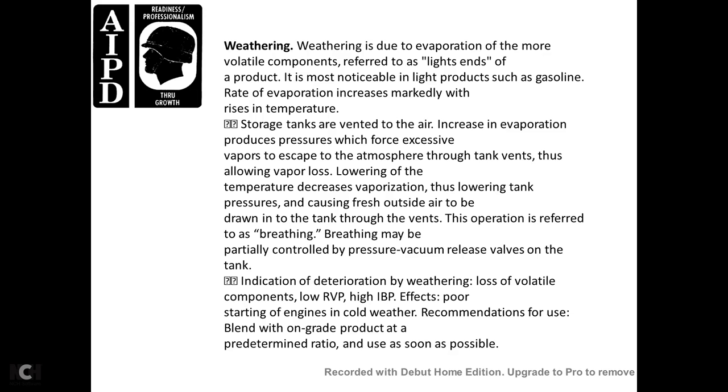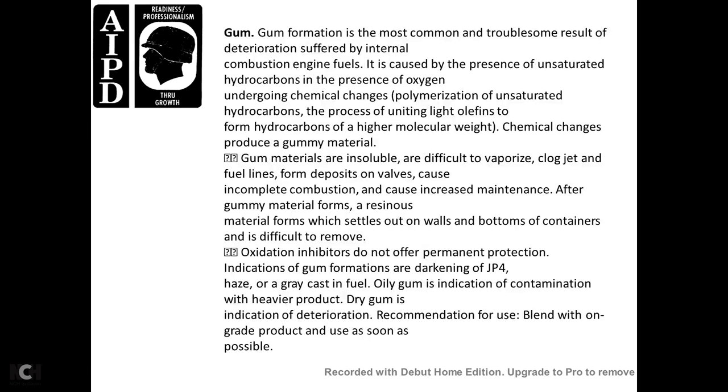Identification of deterioration by weathering: loss of volatiles, indicated by low Reid vapor pressure or high initial boiling point. Effects: hard starting of the engine in cold weather. Recommendation for use: blend with on-grade product at a predetermined ratio, usually as soon as possible.